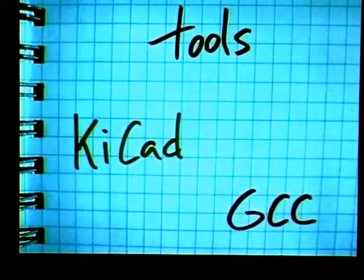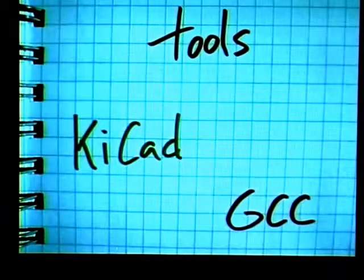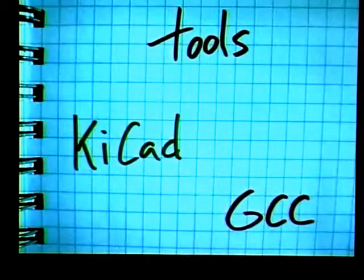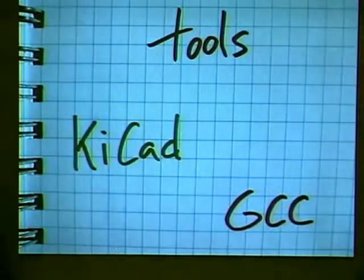So I want to talk a little bit about the tools that we used in HackRF. To start with, the hardware design was done predominantly in KiCad, which is an open source schematic capture and circuit board design software. Mike did the bulk of that work, in fact, all of that work. We used GCC and GDB for ARM to develop the firmware for the HackRF processor. Used OpenOCD for debugging the processor over JTAG or serial wire. DFU util for downloading code to the processor over USB. Python and C have come in handy in order to interact with the device over USB, and we're also using Make and CMake as our make systems throughout the project.